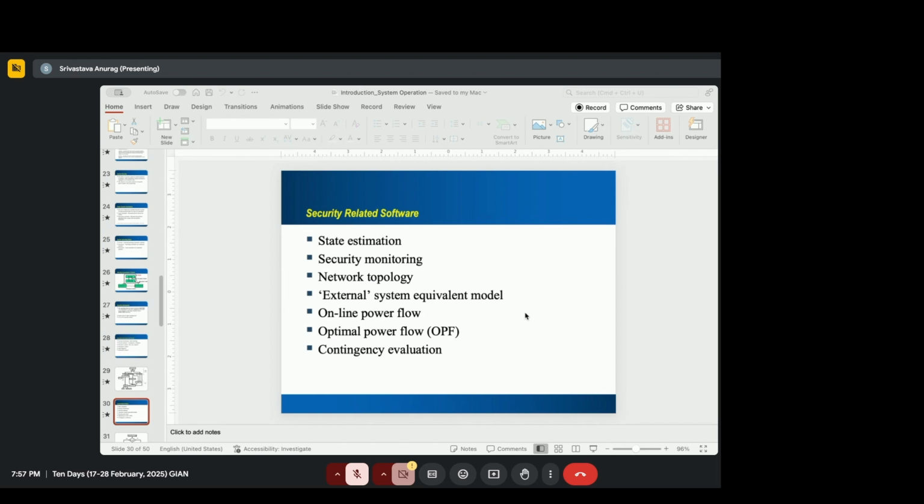For dynamic state estimation based on the PMU, one requirement is that you have to have a fully observable system, which means that every node has to have a PMU with all the lines and all the nodes being read by the PMU. Because if you don't have that, then you don't have full observability and you cannot solve it.